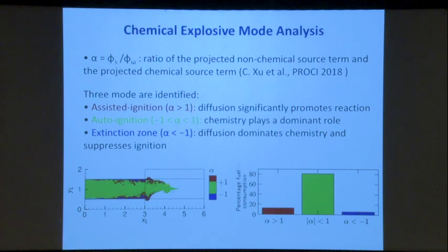And so the green regions here are indicative of autoignition occurring, whereas the red isocontour regions show the existence of flame propagation assisted by ignition, and blue along the cold boundary layers are regions that could be likely subjected to heat losses and quenching.